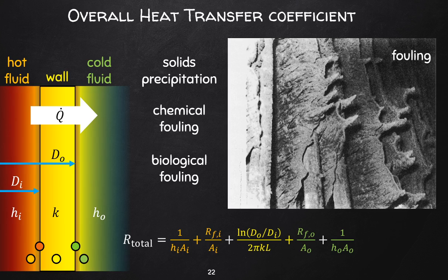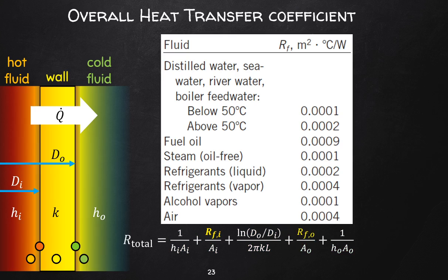There's a little filter on the tap that usually picks up all the sand particles, but there's sand sitting in your geyser. Your geyser's filling up with sand as you watch this video. So whatever the fluid, fouling is most likely to occur in some form or other. So just accept it and deal with it by adding it into your calculation.